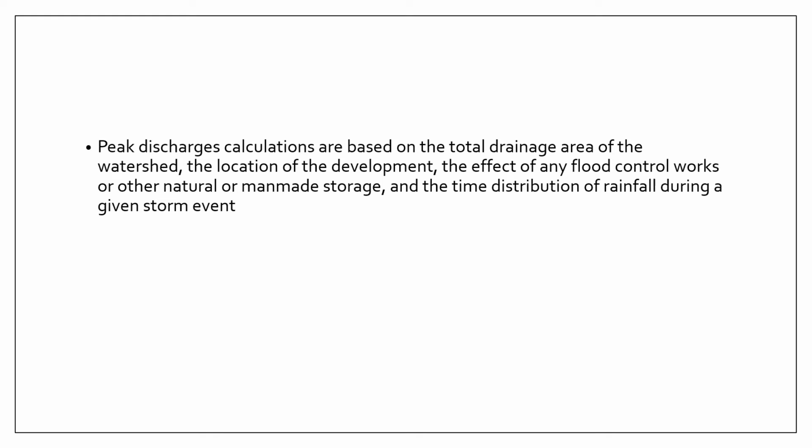So you can actually determine how much the stream flow will spike for a given rainfall. This is important if you're doing flood studies, because in flood studies the flood occurs once the stream flow or the river flow spikes. But for this lecture, I won't be discussing how to calculate the peak discharge. I'm just dropping off that you can determine the peak discharge from the SCS-CN. So let's just focus for now on the infiltration component and the runoff of the SCS-CN method.